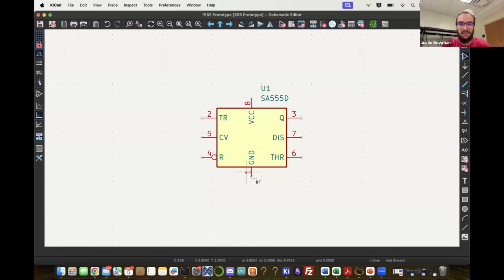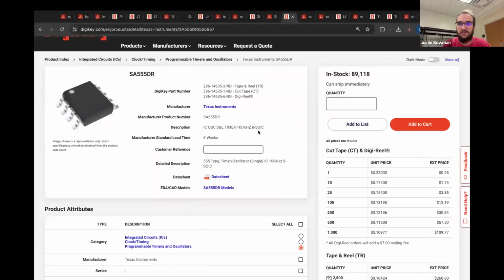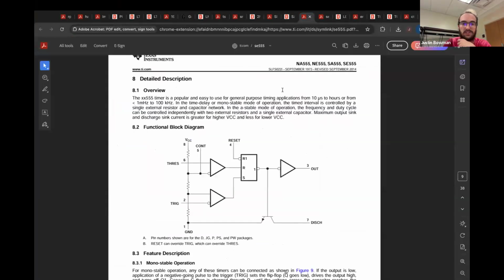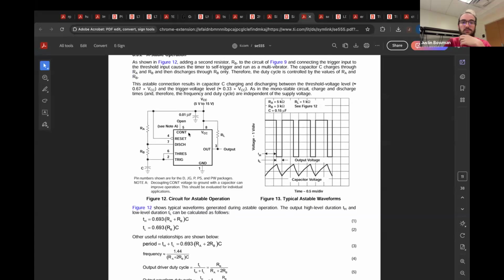So basically what we're going to do is go through each pin and figure out where it needs to go. And that is told to us by this datasheet. So from here, we see that we need 1, 2. I don't know why this load resistor is there. I looked at other datasheets which didn't have it, so I'm going to omit it from our design. But we have 2 resistors and 1.